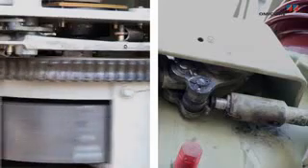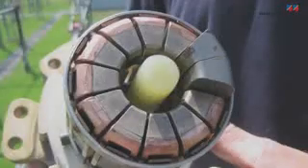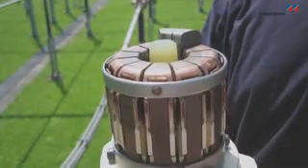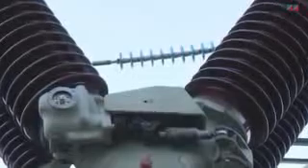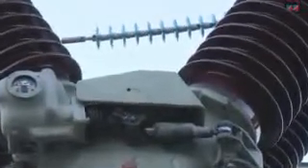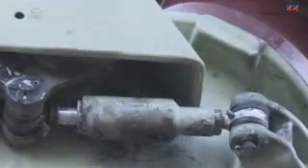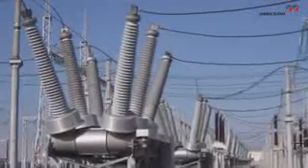The interrupter and the mechanical drive are the main components that are subject to wear and aging. The thermal stress of load currents may cause corrosion and oxidation, and the interruption of short-circuit currents erodes the contact system. Environmental stresses, such as temperature, humidity, or contamination, affect the bearing and linkage surfaces of the drive. Ancillary components, such as bushings, are also subject to electrical stress aging.